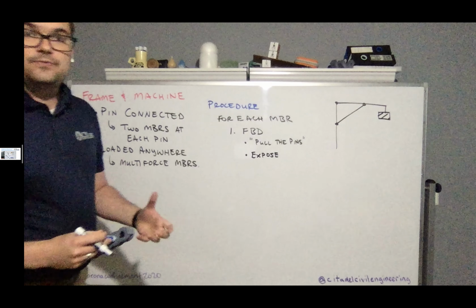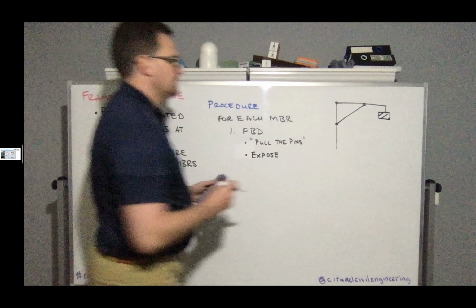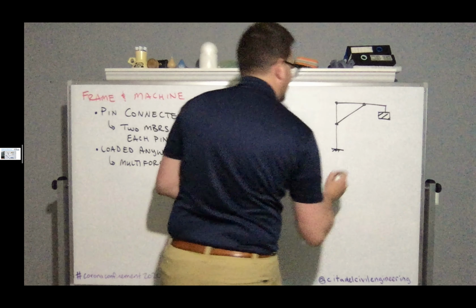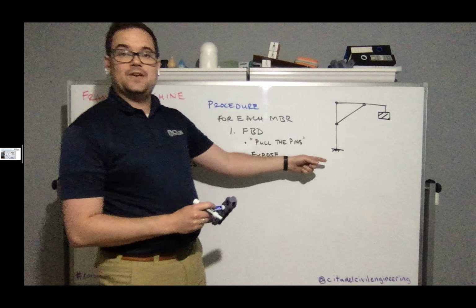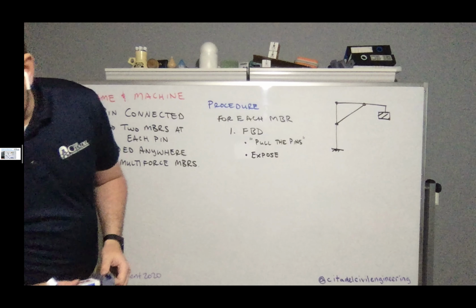the joint forces. So currently, if we were to solve for the external reactions on this frame, here we can even put in a connection to the bottom that's a fixed connection. So it's going to have two forces and a moment acting on it.